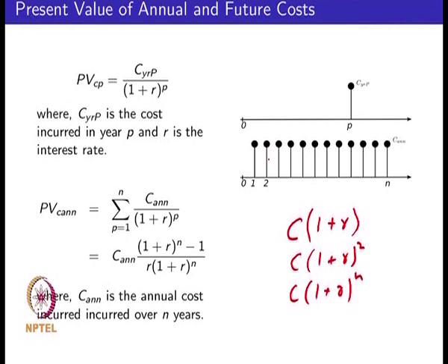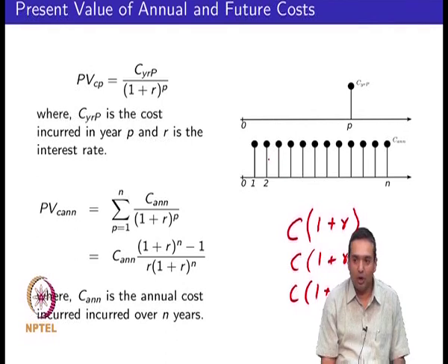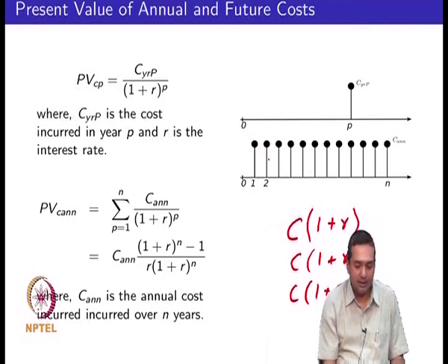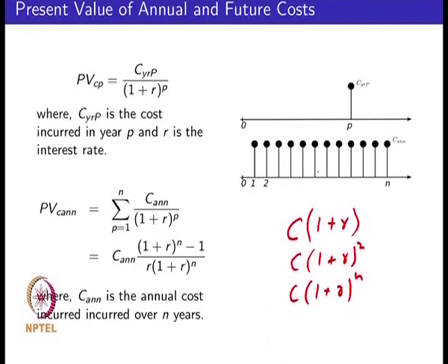So, in this example, annualized cost might be the losses that you incur in a power converter. You might know how many kilowatt hours of loss there are, and you know the cost per kilowatt hour for electricity. So, in a way you can reflect back the losses to an upfront number at the initial point to look at what is an effective cost. Many times what can be encountered in the future can be reflected back to the present to see overall what would be the benefit of making one decision or the other.